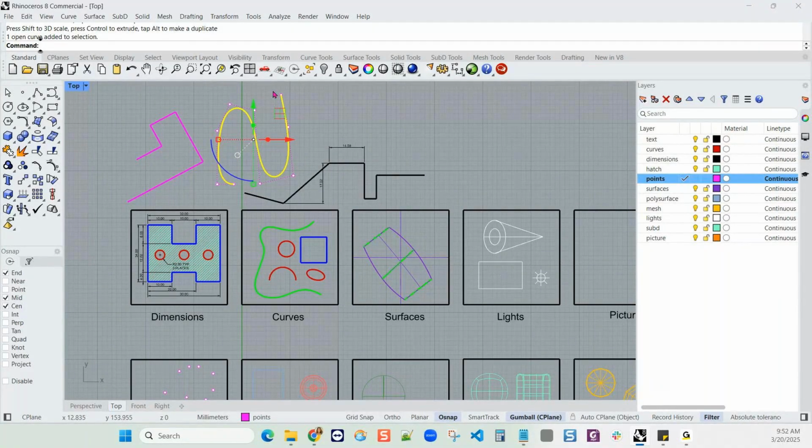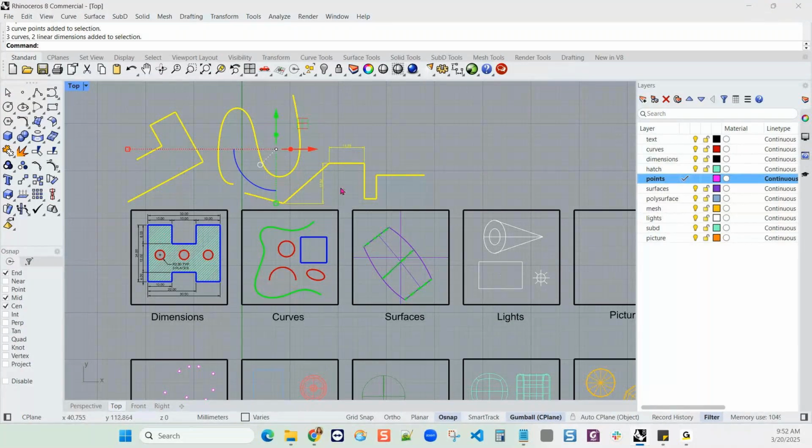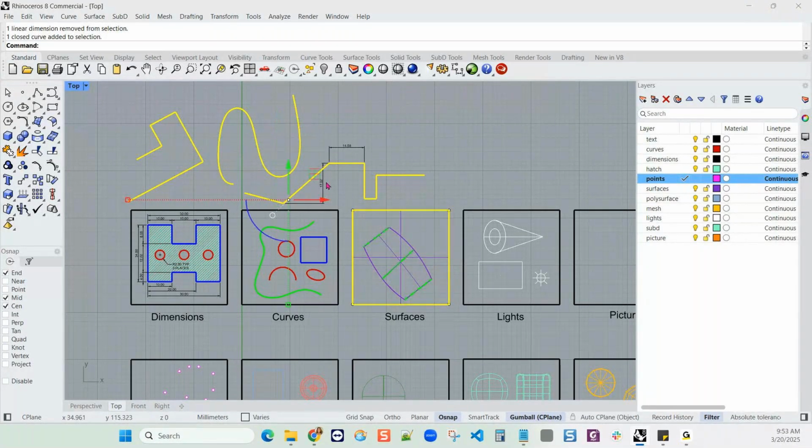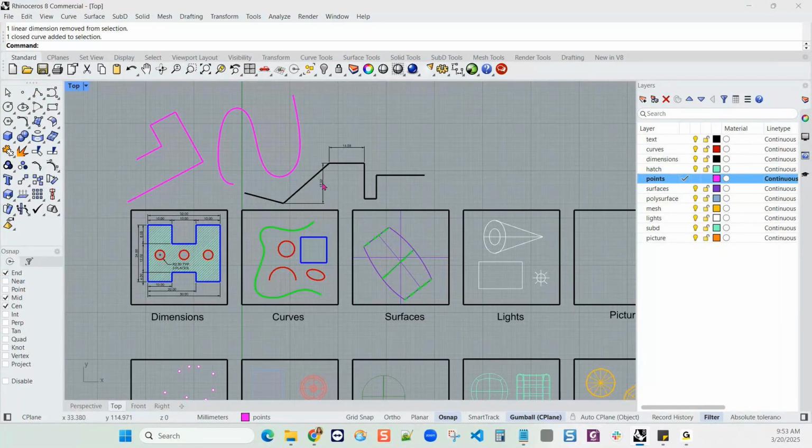I can also move a window of geometry or control points. So if I pick those control points and I type in 5, then it moves those control points 5 units over. In Rhino, you can do a crossing window to select everything. You can hold the Control key down to remove from the selection set. You can hold the Shift key down to add to the selection set. So just basic Windows selecting plus a few little bonuses when you're inside the Rhino viewport.